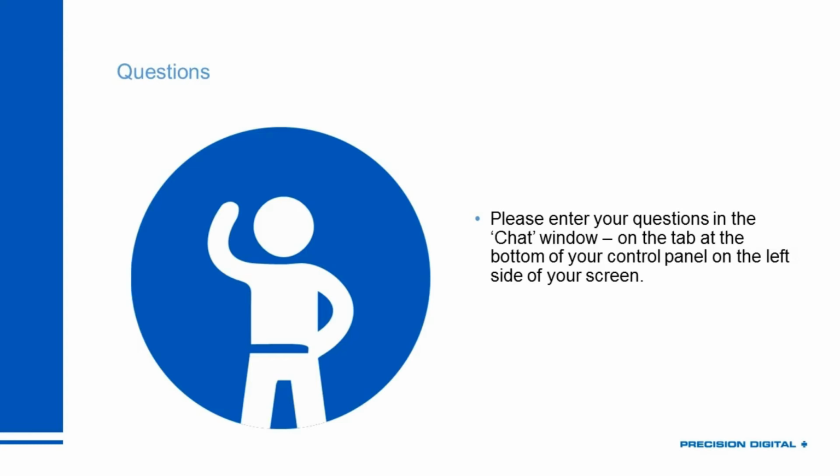So to clarify Jim's question for everyone, what he's essentially asking is he's got a 4 to 20 milliamp loop. And for the sake of this webinar, we'll assume he's got loop-powered devices in it. So he has a 24-volt supply that's driving his 4 to 20 around the loop. Well, that is fine, having an external supply like that, if you have a passive 4 to 20 output on your transmitter. Because passive means that it doesn't provide its own power for the 4 to 20 loop. It needs that external power supply.